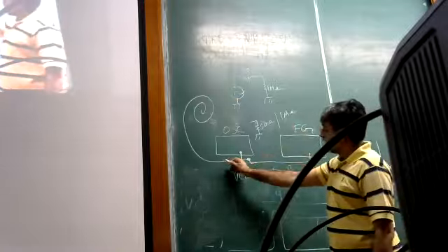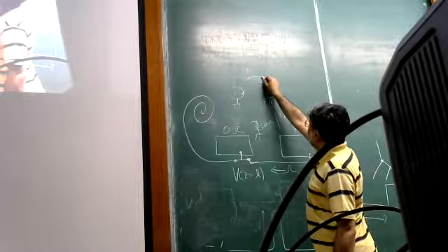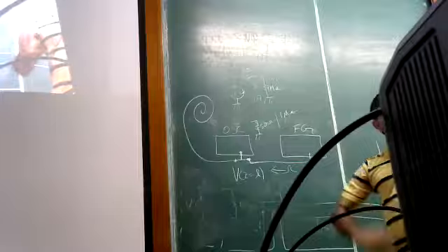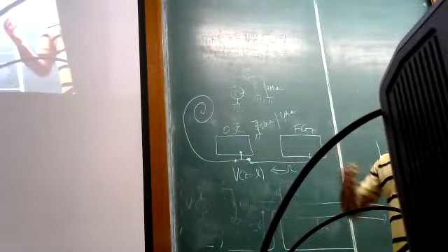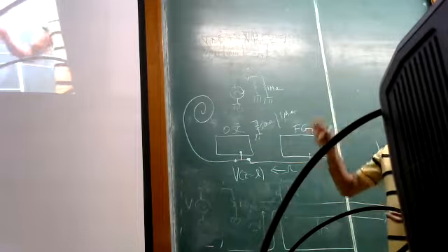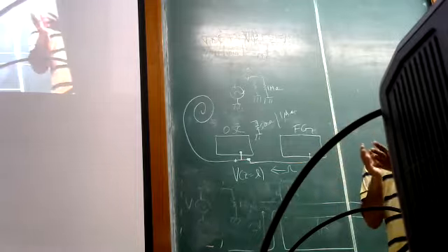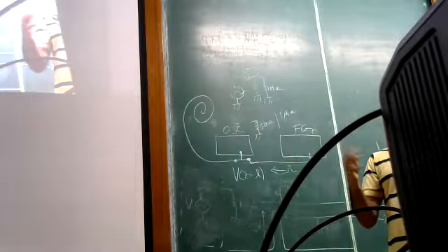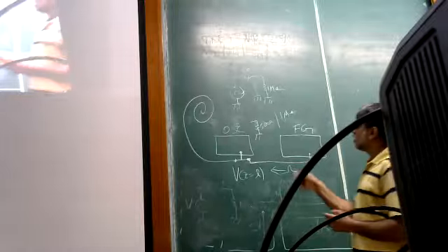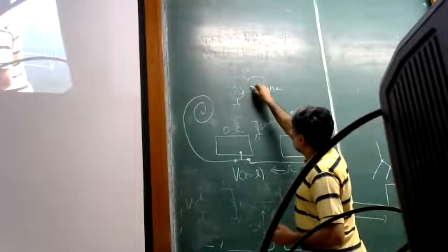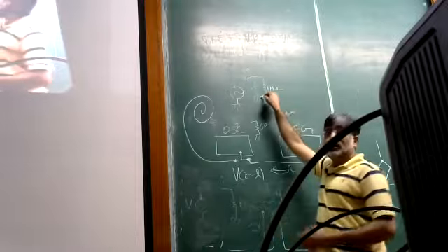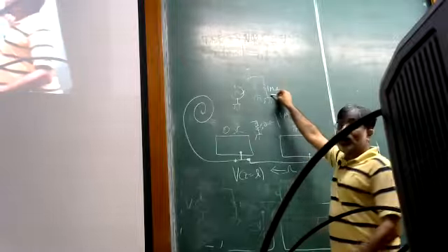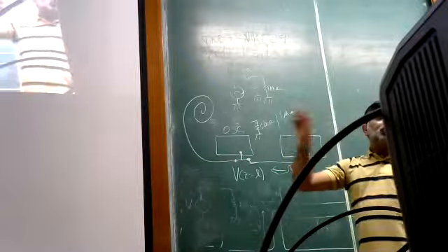Now, when we have connected this cable here, that's equivalent to putting another 50 ohms across it, right? But again, momentarily in time, because the cable is not terminated on the other side. But remember that the scope signals are local in time. When we see a certain voltage rise and fall, that is happening at that particular time. There's no steady state picture in the same sense. So the moment you put a 50 ohm here, the voltage drop across these 2 points becomes half of what it was before. And that's the same voltage drop that's going to be across the 1 mega ohm as well, which is what the oscilloscope is going to display on the screen.